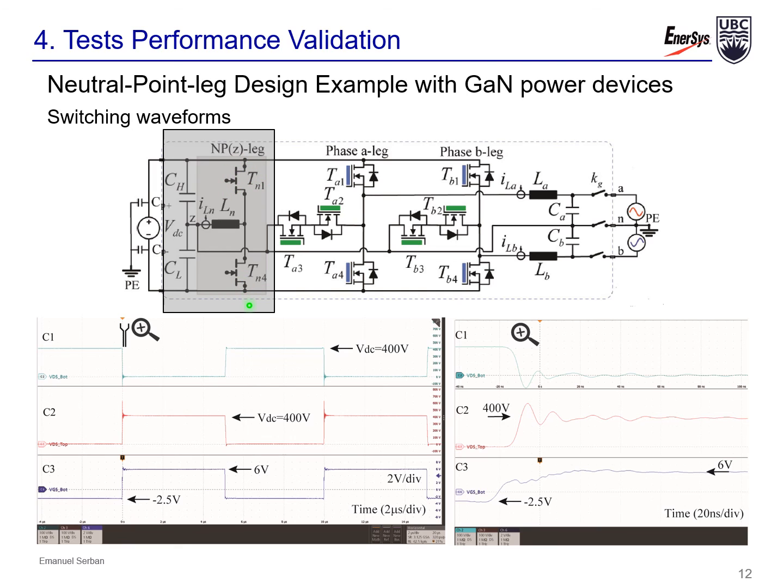The neutral point leg regulates the high side and low side to approximately half, let's say 200 volts each side of the capacitor. The neutral point controller ensures the converter's safe and reliable operation under any load conditions.